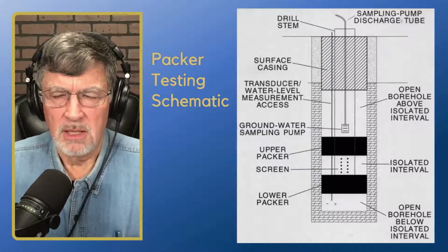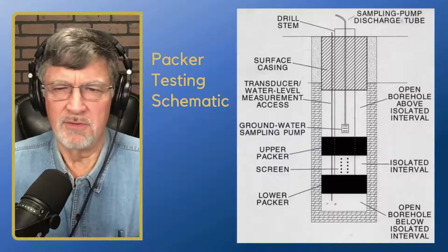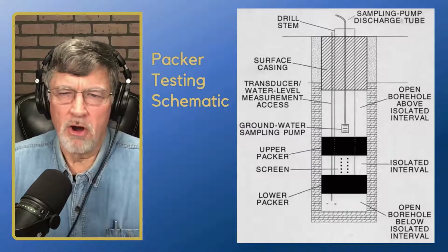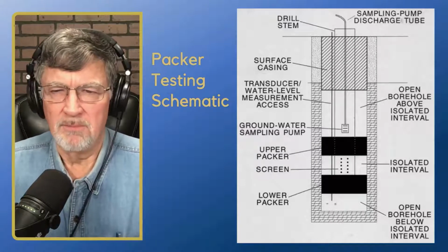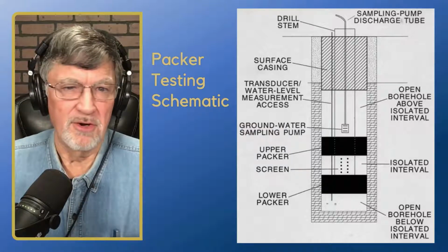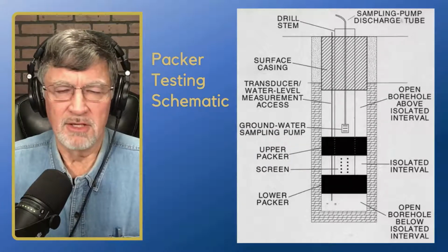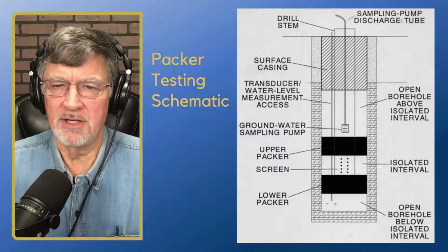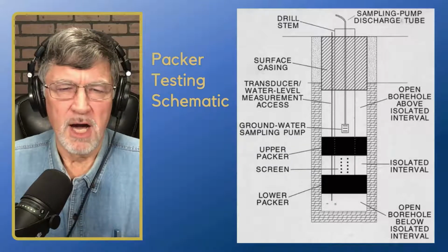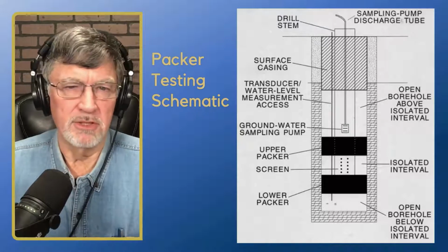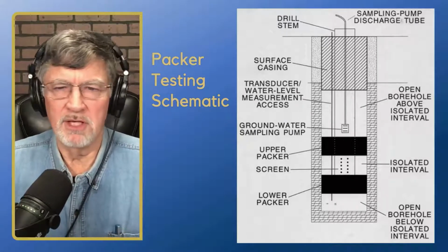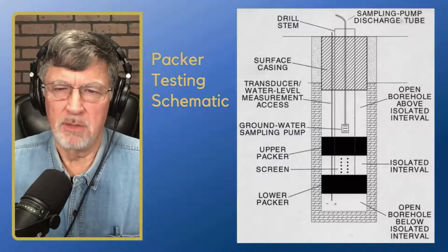So this is a limitation of the straddle packer setup, because it's hard to adjust for the amount of screen you have. So you're probably going to do a standard 5-foot interval, or you're going to have to determine that ahead of time. So that can be kind of challenging. If you're at the bottom of the hole, you may only use one packer to isolate that zone. But anything above that, if you're isolating zones, it's going to be a straddle packer setup.